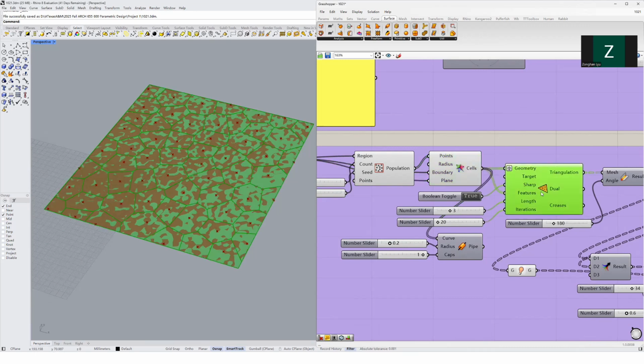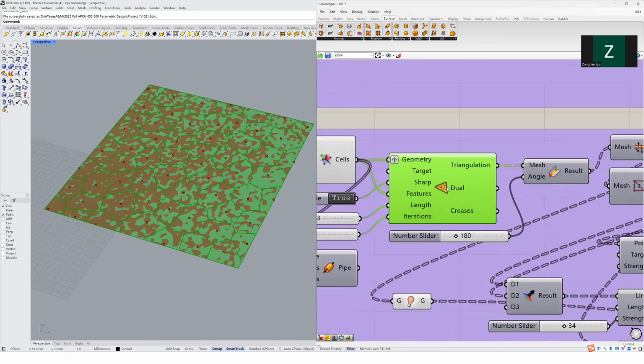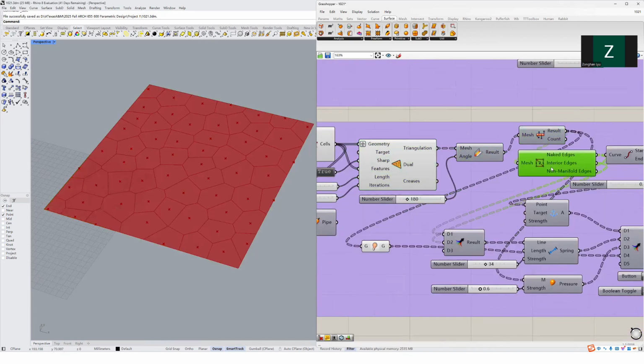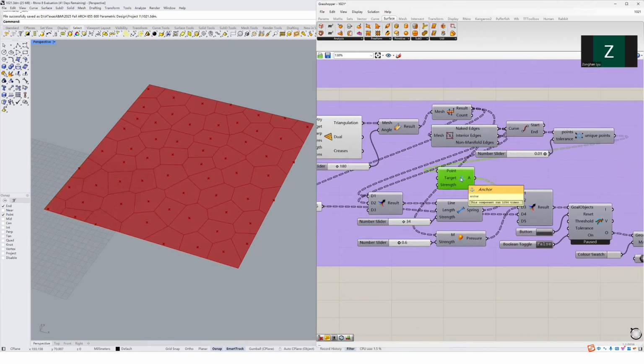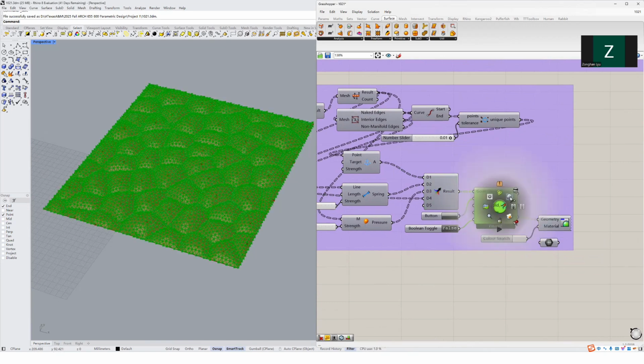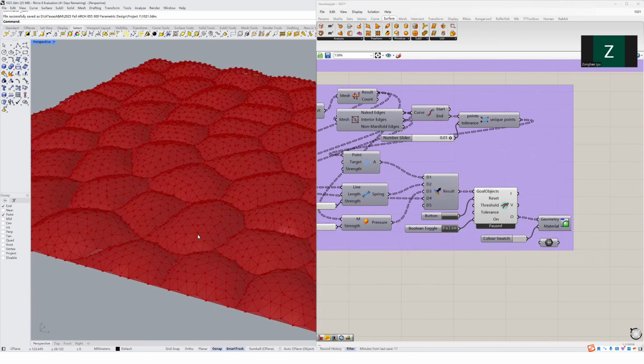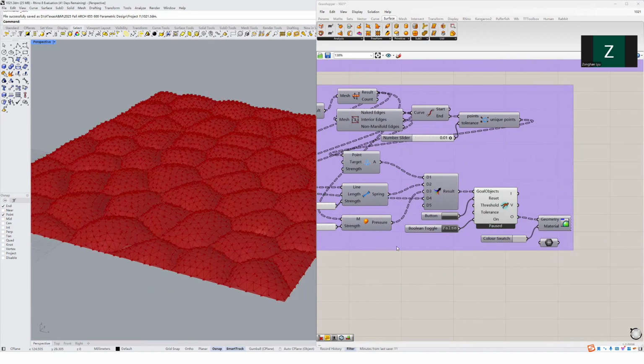And then subdivide the surface, use this tree mesh, and next anchor those points, and then set the length of the lines, and then give a pressure to these meshes and merge this result, and then use the solver from the Kangaroo to generate this bubble-like and film-like facade.